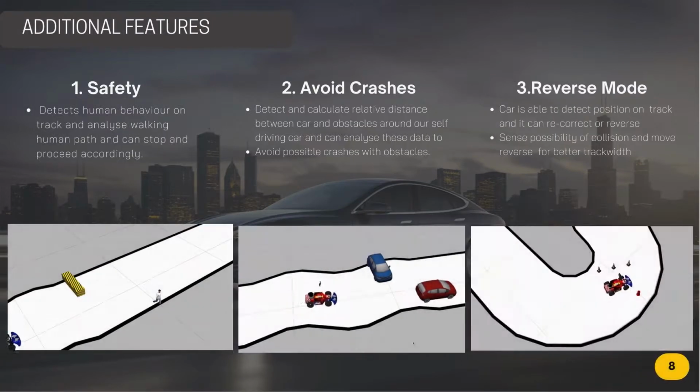In order to attain self-driving capabilities, we have added pedestrian tracking based on laser object localization, which enables the person to cross the road based on the direction of motion. We have also added collision avoidance based on information from the laser sensor and track information. The car also switches to reverse mode when blocked by any obstacle, based on odometry, and reattempts to navigate.